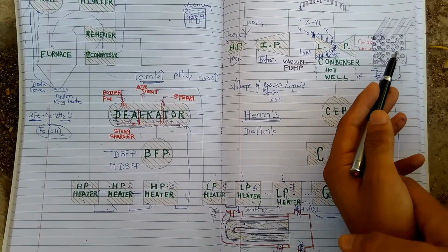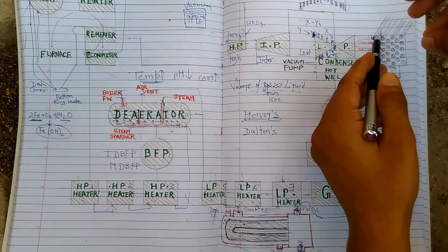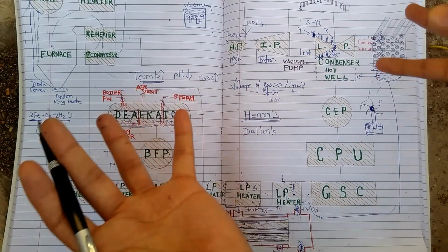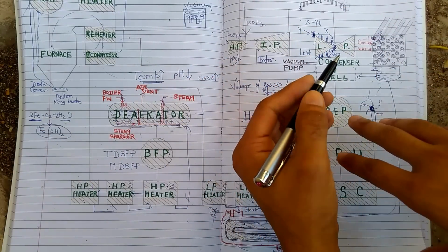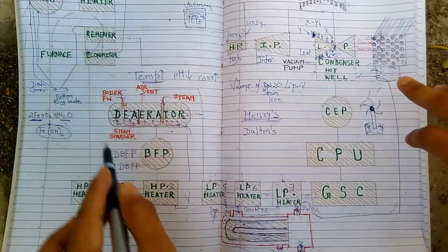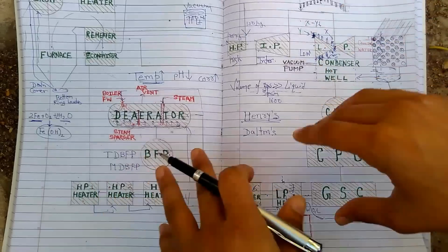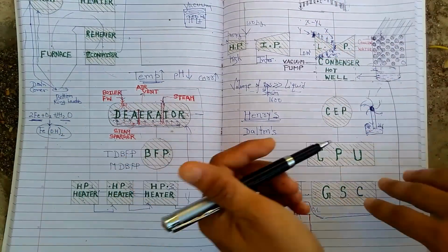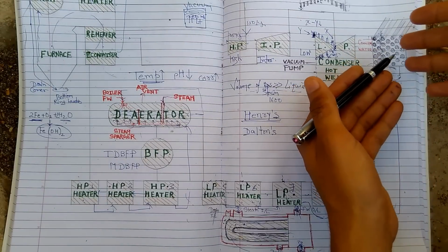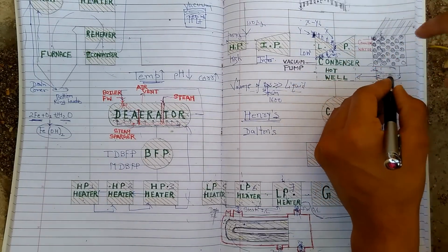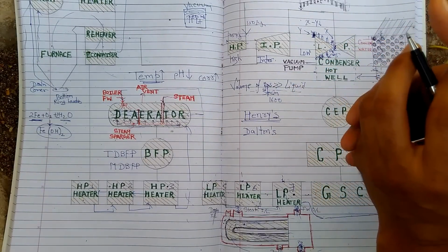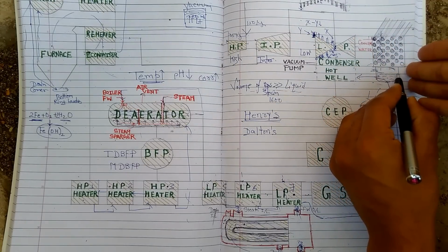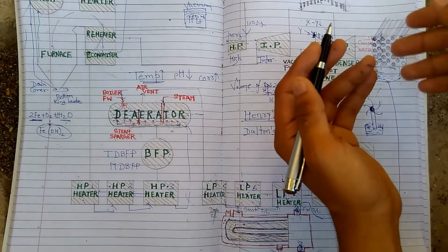Similarly the vacuum is created here. You have steam. Now you are condensing the steam, then the volume of that steam will decrease after condensation, and as this complete system is closed, it does not have any ingress from the atmosphere, it is a closed system. So if you condense the steam, then naturally the vacuum will be created in the condenser, because now the steam has converted into water and volume has reduced, so in the remaining part there will be vacuum.